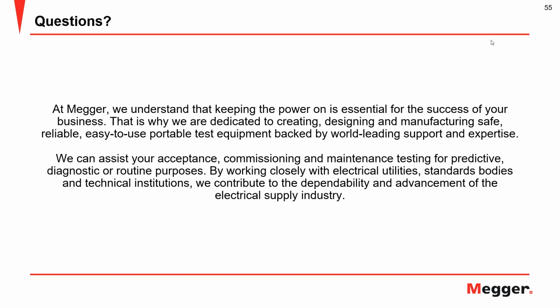Most of the non-conventional testing was invented for substation equipment, for transformers, for end terminations, and for switchgear environments with short runs, where you can still pick up high frequency components of PDs and where you have access to the shields and everything. So for this, you have non-conventional PD analysis.